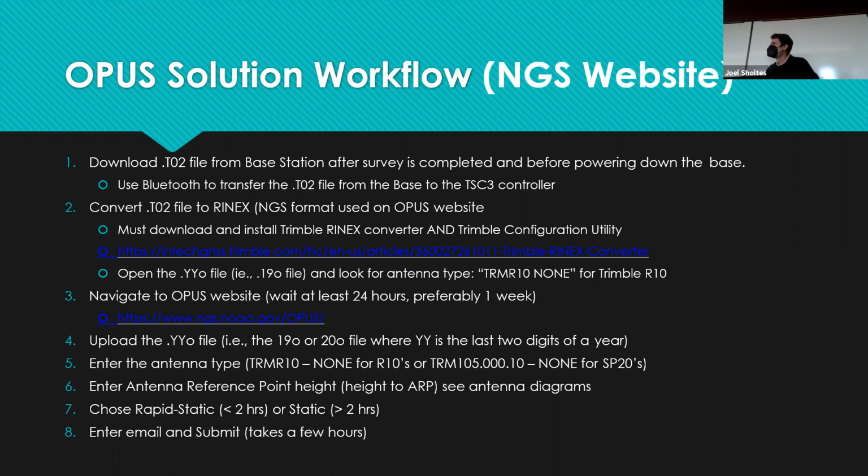All of the rest of the data, it all happens automatically. So we'll see in Trimble Business Center in a second. All of your survey points from your rover are vectors off of the base station. It's all relative to the base station. So when you shift the XYZ, all those vectors are going to shift in XYZ as well. So it's an automatic update. It's pretty slick.